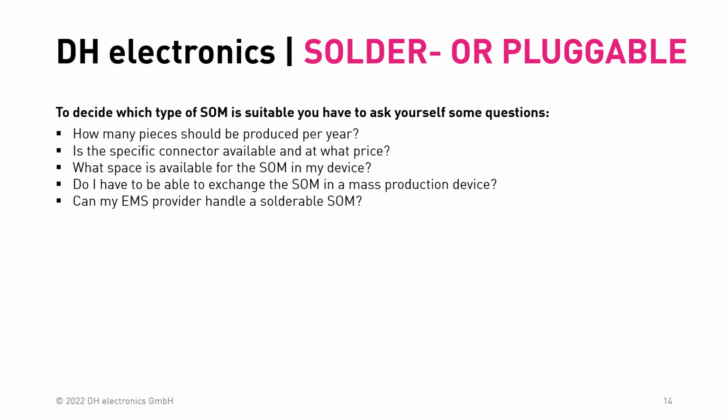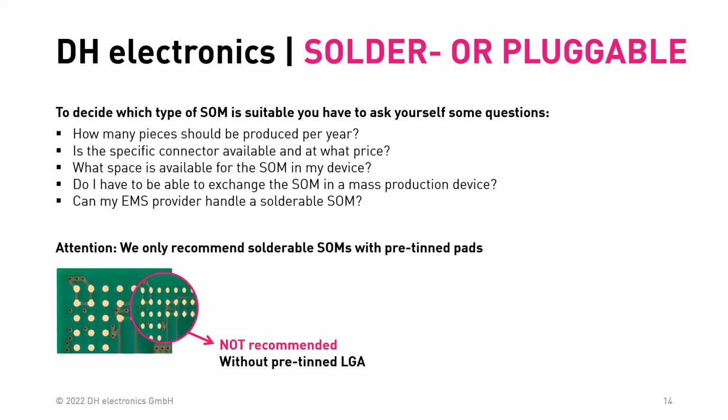And the last question: can my EMS provider handle the soldered down system on module? Here we like to have a look at the LGA solutions, the land grid array solutions on the market. Here you can see a solution without pre-tinned pads, and this we as DH Electronics really do not recommend, because it is not a safe solution for production.